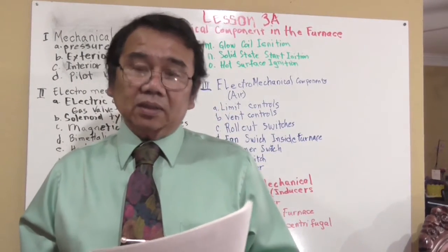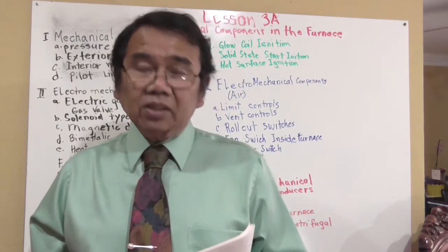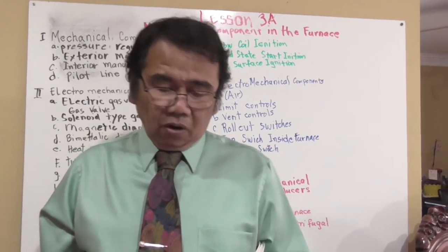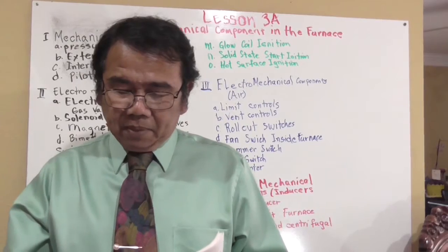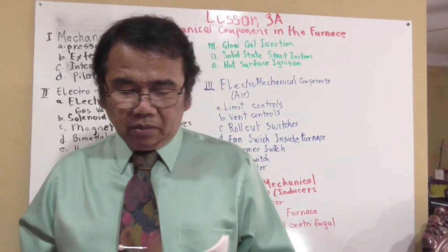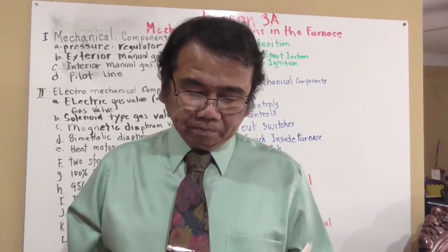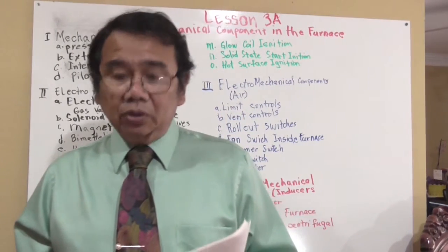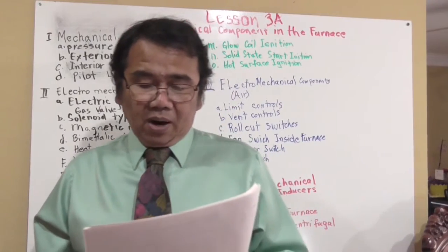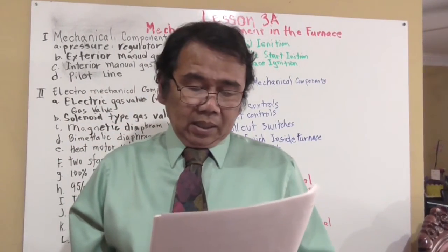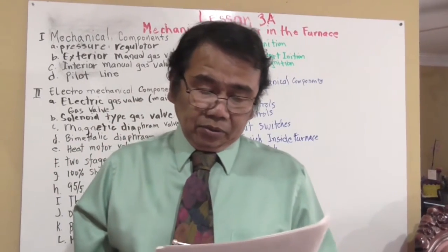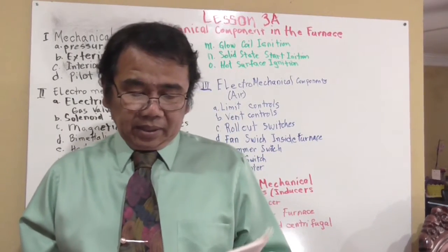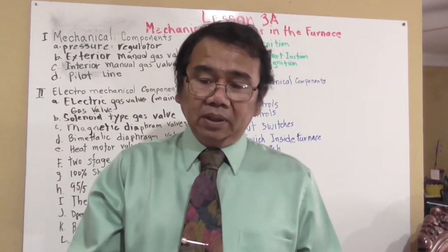When the G wire from the thermostat energizes the coil in the relay, the normally open contacts close and the normally closed contacts open. There should be supply power at the common terminal of the relay. The high-speed wire from the blower should be connected to the normally open contacts. The supply wire for the fan control should be connected to the normally closed contacts of the relay.